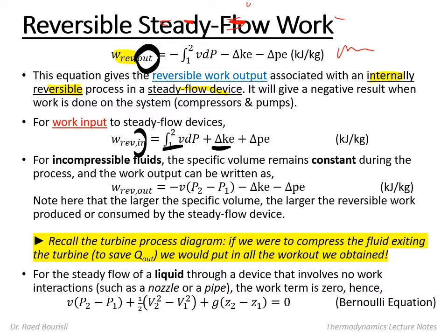What this is saying is that the minimum work input is whatever I increase the potential energy and kinetic energy of the fluid that is being compressed, plus whatever boundary work I need to put into the fluid being compressed, and nothing else. I don't need an extra something for the irreversibilities, for example.